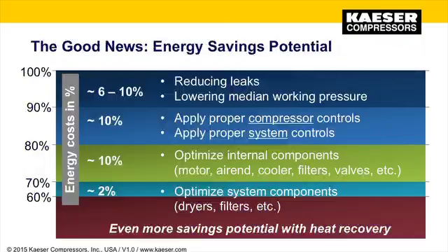If the prevalent attitudes can be overcome, there are a number of very effective ways to make improvements. Applying any of these strategies can give you noticeable energy savings. Fixing leaks alone can easily create energy improvement of 6 to 10%, and this is honestly a very conservative estimate. Choosing proper compressor controls and controlling multiple compressors from one device also offer significant savings and offer improved pressure stability.